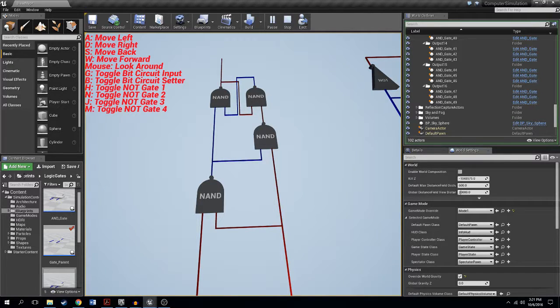And now we see that something has happened. Our NAND gate is now off and our output is now on. And so we've now turned on our output. This is where things get a little bit trickier with the feedback loop. So we see how the feedback loop has now switched position, where it's now the top left that's on and the top right that has an off output. So I'm just going to go over the functionality a little bit here. I hope you can understand the logic behind it.